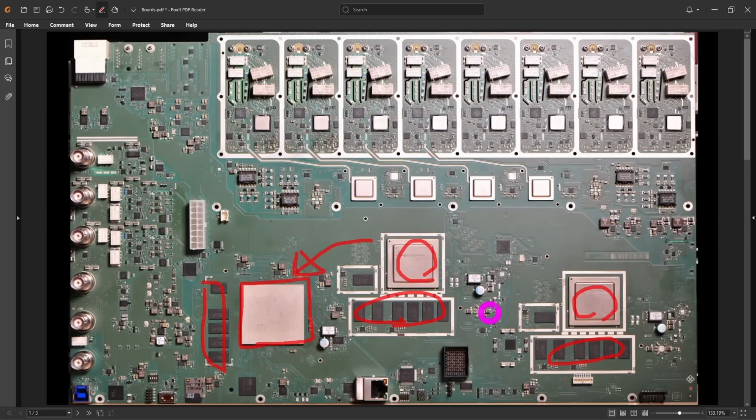You want to keep that as contained as possible because you're just a few centimeters away from the acquisition front end. So not only is all of this custom, all the ADCs in the front end are also fully custom, and the front end devices, the analog conversion devices in the front, are also fully custom. So yeah, if you remove those from this, there's really not much left. All the signal integrity and all the noise and all the bandwidth and the linearity you're going to get from the front end has to be brought in by the custom ASICs, and that's so hard to compete with.